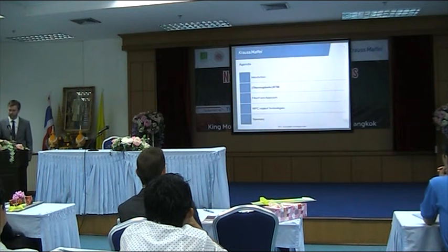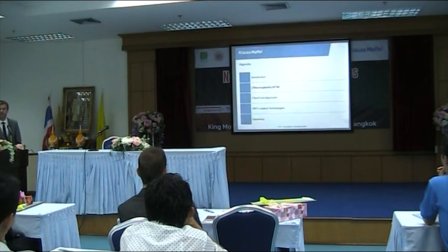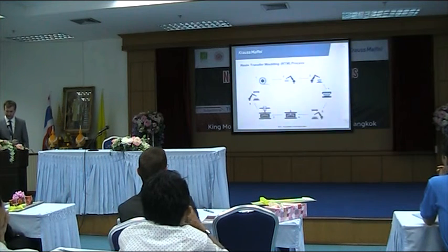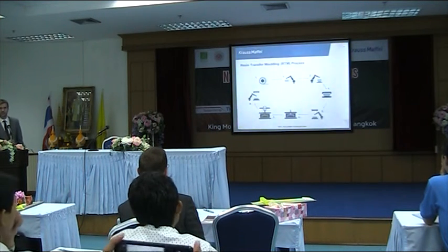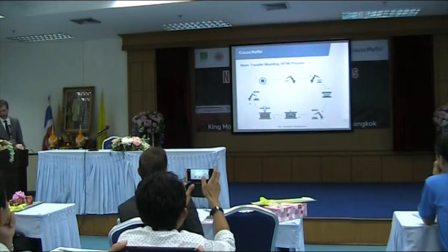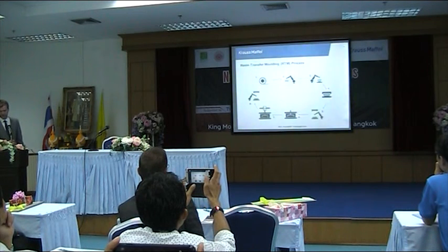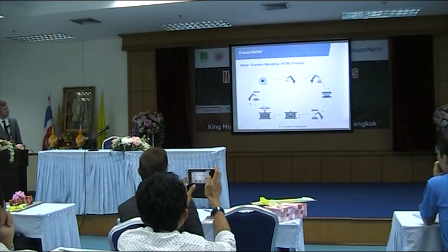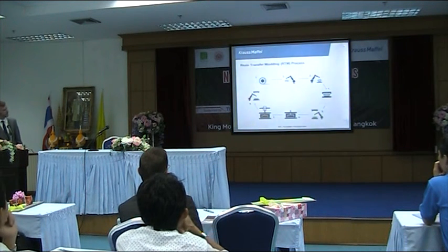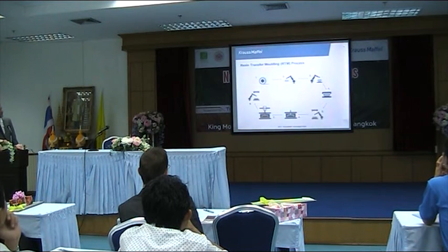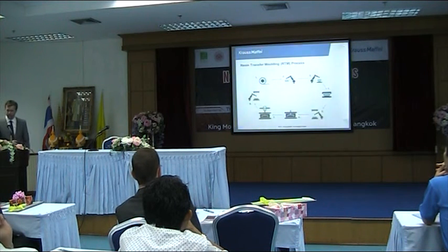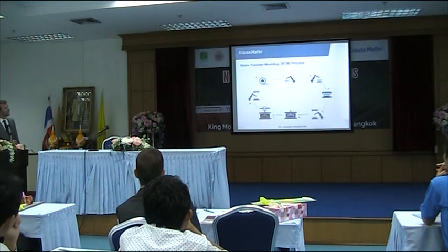Let me give you a focus on resin transfer molding on the thermosets. The process, I think, is known to you. You have the material, so the tape. It will be cut out and stacked, and then it may be formed and put into the mold. It is evacuated, and then the polyol and the isocyanate are mixed up and injected into the mold under high temperature and high pressure. And then you take out the part.